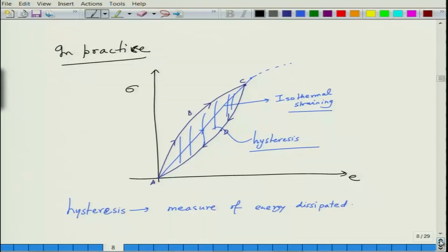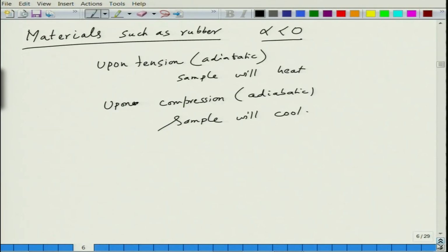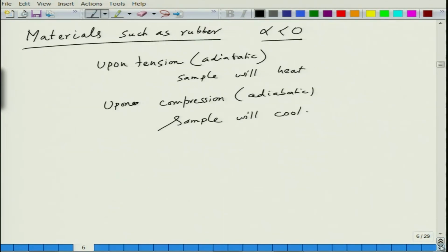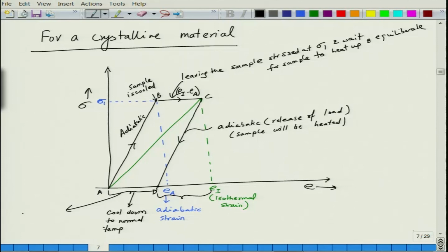What we have done in this lecture is we have looked at the hysteretic process that we obtain in case of inelasticity. Isothermal straining of a material would directly take you from 0 to a certain strain, let us say epsilon 1, the isothermal strain. However, in reality, if you load it too fast, at a rate when strain does not follow the stress, then you will not achieve complete strain, and you will have to leave the material for a certain time to achieve complete straining.